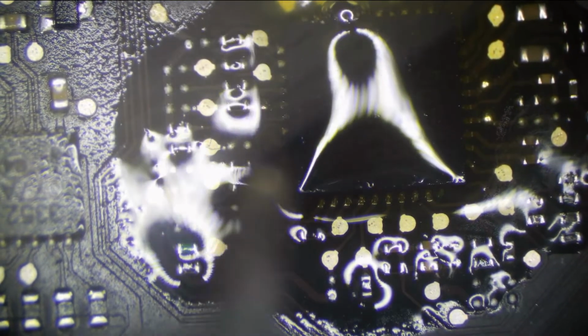Another thing I've seen is people completely destroy these boards with Radio Shack irons. If you have a Radio Shack iron or anything like that, don't even attempt to do this. You need a good iron, preferably a Hakko or whatever you can get that has a small tip like this. And please know how to solder QFN chips before you attempt this. Practice on a donor board, not on your first customer's board, just so you get a feel of how to do it. Once you do it successfully on someone else's board, then you can do it on your own, or on your customer's board, I should say.